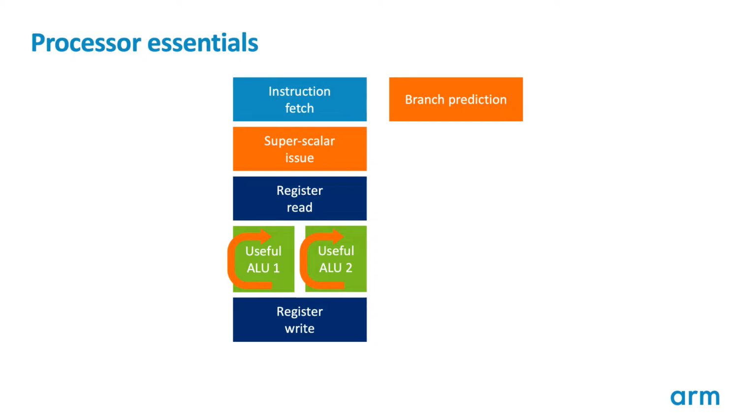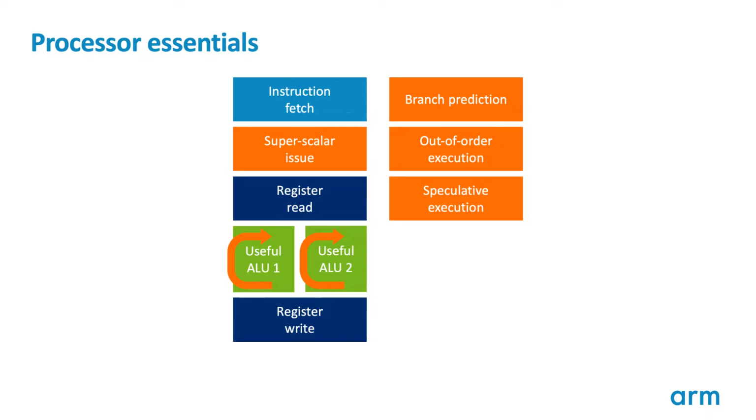For a modern processor, simple in-order parallel issue can't find enough parallelism to keep the wide instruction dispatch busy. So, high-end processors generally include some form of out-of-order execution, which allows the processor to find parallelism present in a large window of instructions, and issue those instructions as soon as they are eligible. Many processors use speculative execution, filling in idle units with operations which might be useful. For example, executing both the if and the else of a conditional block, and keeping the result that is actually needed.